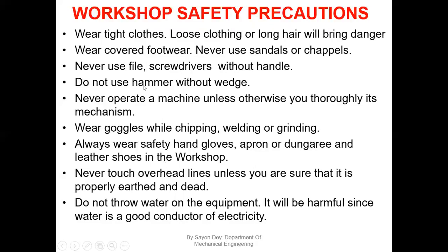I'm not going through all the points, but I'm highlighting some, like wear tight clothes. Wear covered footwear, which I have already told you. Never use files or screwdrivers without handles, as that may cause an accident. Others are there too: wear gloves during chipping, welding or grinding, because the chips may enter our eyes. So our objective in workshop practice is to do work, but we have to be careful about our work, because at any time an accident may happen.